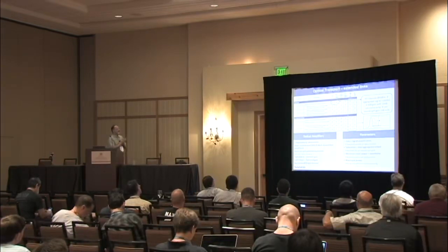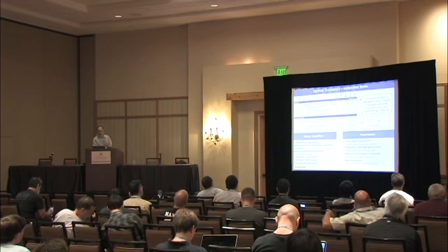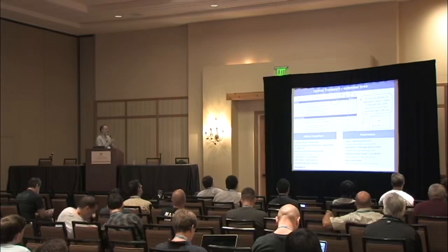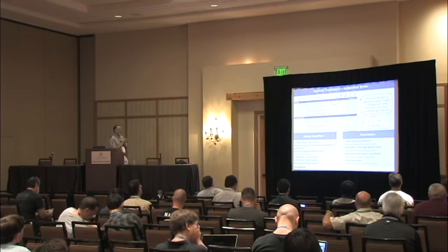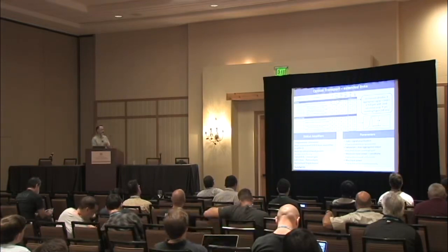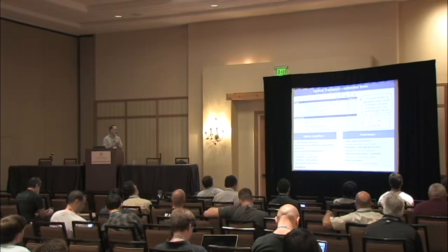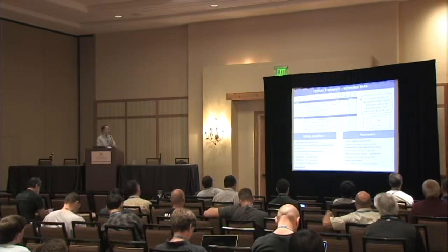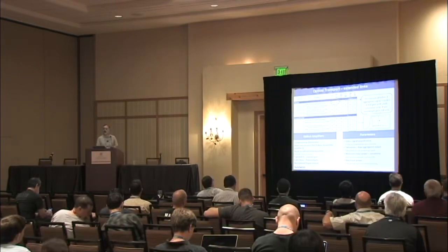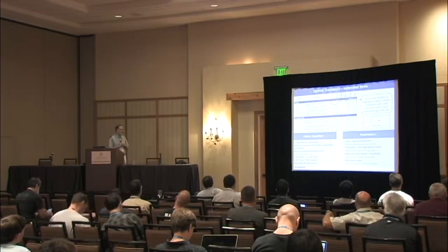About amplifiers, we put some amplifiers here as examples, and we are going to look at different parameters. The most common in the industry are EDFA, erbium doped fiber amplifiers, and based on the position in the network, in the link, you are going to have boosters, inline, preamp. We talked about this. Typically, it's in automatic gain control. The gain is always fixed.